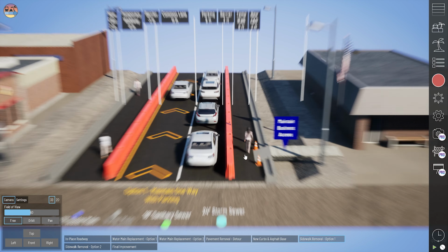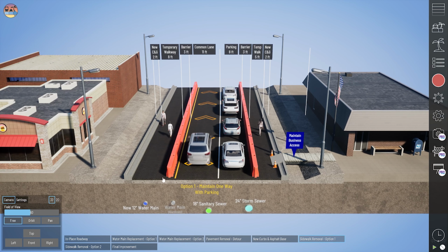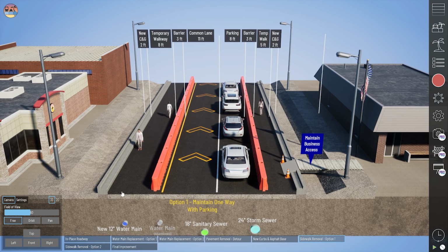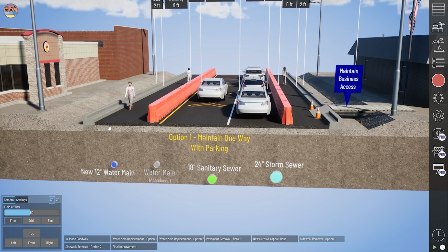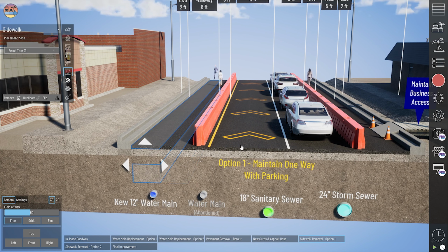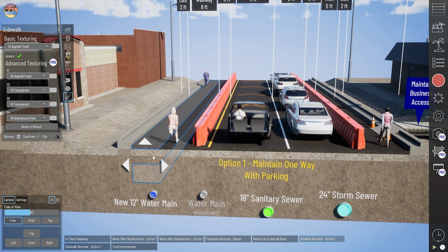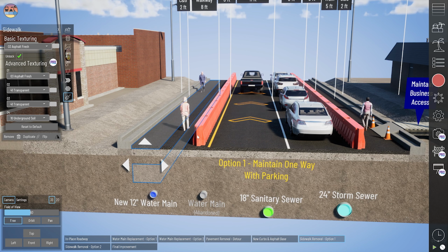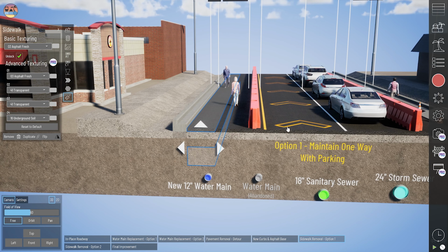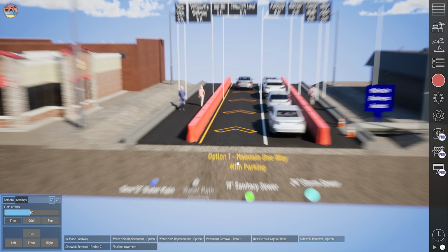that sidewalk demolition area. So again, in this phase, you'll see I've built up an asphalt base and the future curbs and gutter. You'll notice there's some elevation differences there. I've used some earth layers and transparency in some of these sections. If you dive into the advanced texturing, you'll be able to see how I pieced this together so that I do have pedestrians walking on what looks to be the asphalt base of a roadway section.